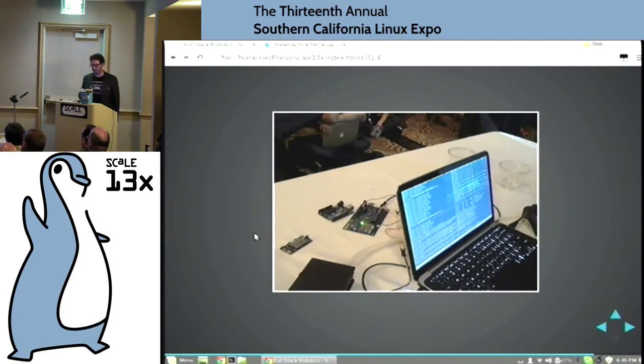So if you don't know, the AR drone runs BusyBox Linux. It's on a 2.6 kernel, so super, super old, right? But we can still run Go programs on there. So I used a BeagleBone Black to cross-compile a Go program to run on the AR drone to control the servo, which I used some Velcro to attach to the bottom of this.